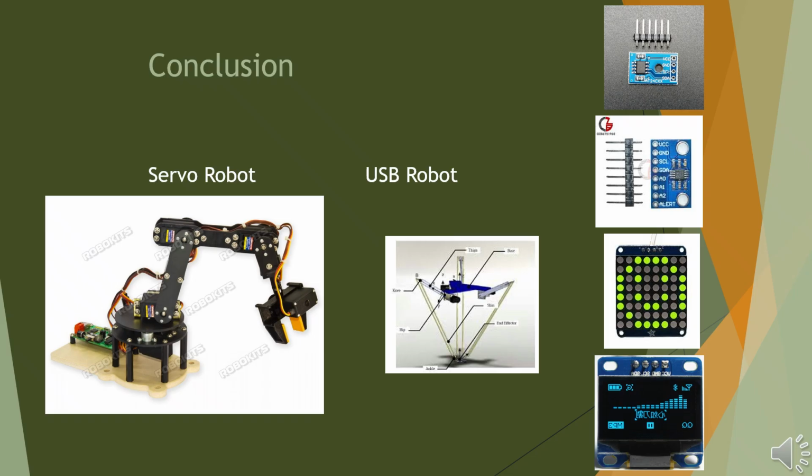A practical example of this can be seen in a robot powered by 5 Dynamixel motors, which all communicate through a half-duplex serial bus. Using a single communication line, the controller can send commands and simultaneously receive feedback on motor positions and states. This bus architecture not only simplifies wiring, but also enables precise and coordinated motion control through a robust, efficient protocol.